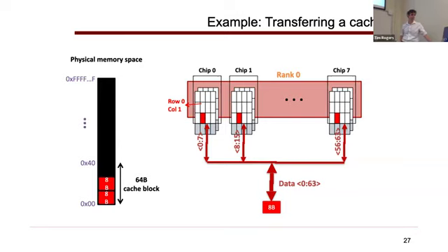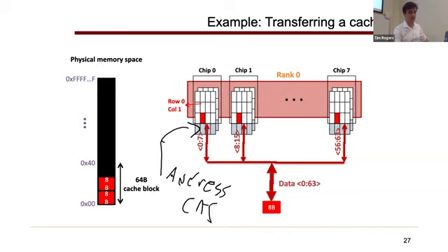Yep. This is still taking 8 memory system clock cycles. But what if, in addition to accessing the next column, we also access different banks at the same time? That's not really possible because you're also pin limited on the address. Every time I go to another column, I'm not showing it here, but there are the address pins. I need to send a CAS, and that CAS has a location, and I can't also send the row command unless I widen my data bus.